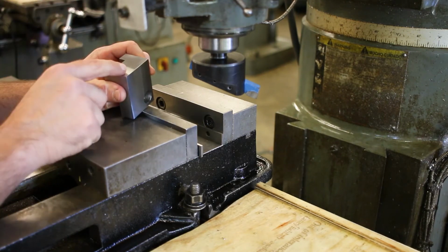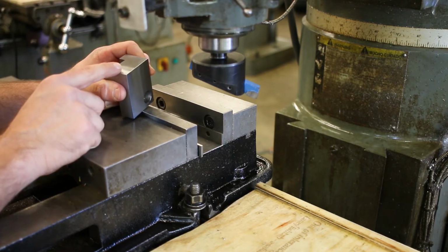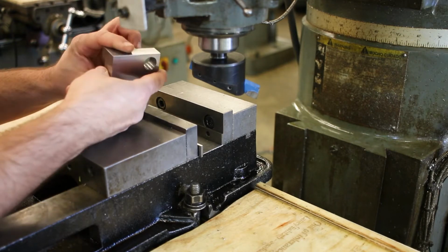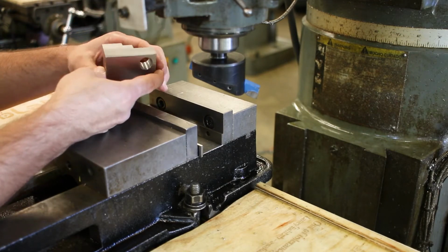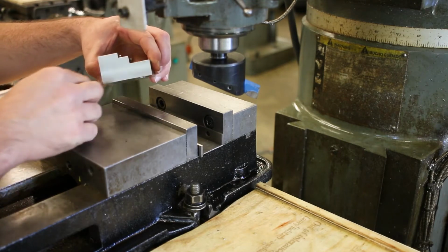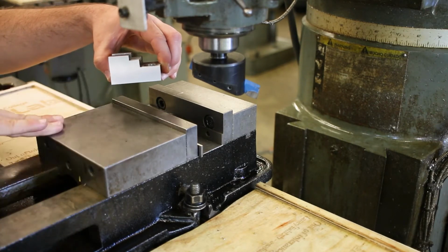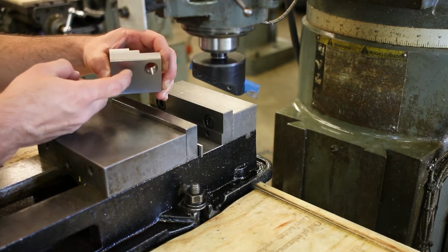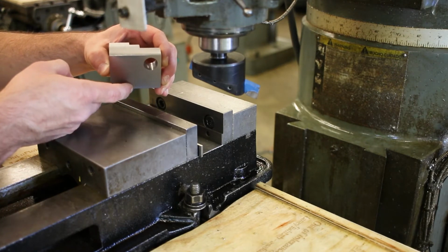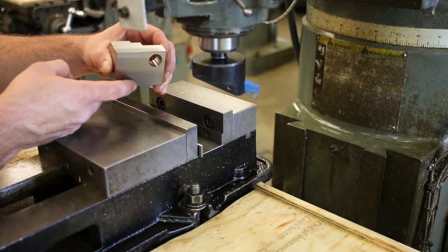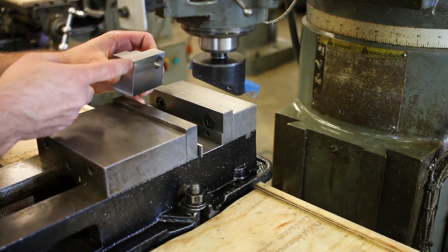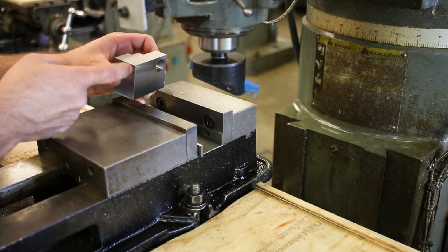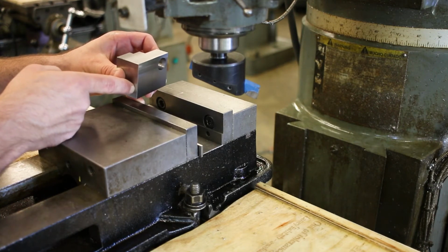Okay, so Datum feature C is finished, and now what we need to do is go in and finish Datum feature D, which is the front surface of the part if you're looking at the front view. So to finish this surface here, again, we want to leave Datum feature A exposed so that we can align it up and down, but we do want some way of getting ourselves relatively perpendicular to Datum feature C as well.